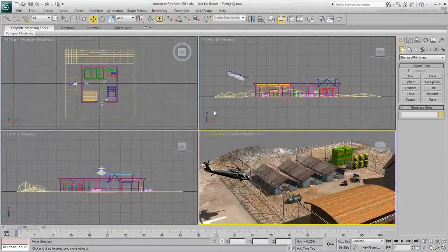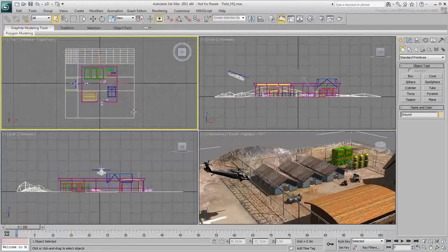The simplest way to select objects in 3ds Max is to use the Selection tool on the main toolbar, and then click on an object in any viewport. The object turns white in wireframe views, and the selection brackets surround the selected object in the shaded view. In the shaded view, you click anywhere on the surface of the object to select it. In wireframe view, you need to click on a wire part, as a hollow part does not work.